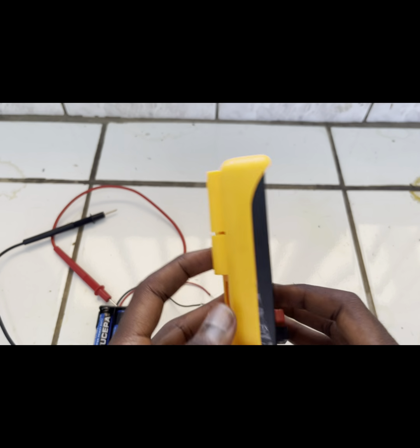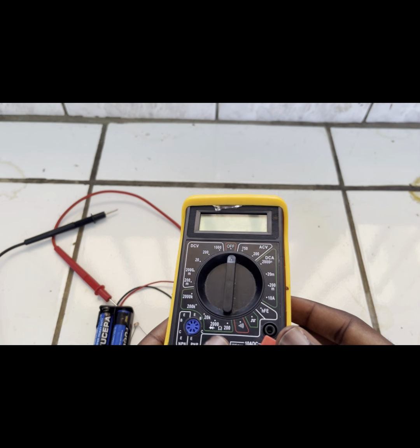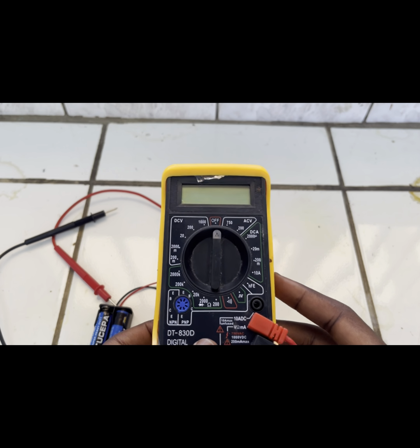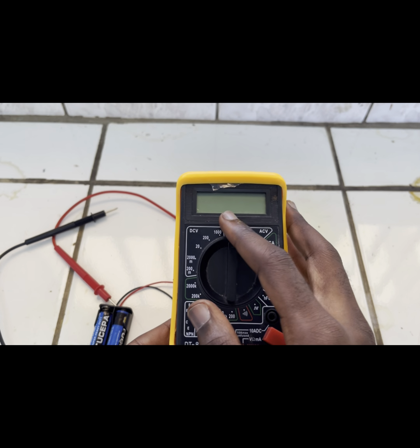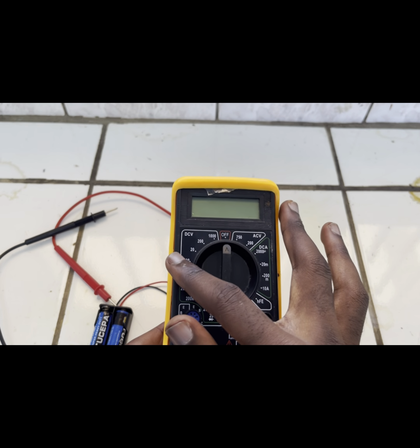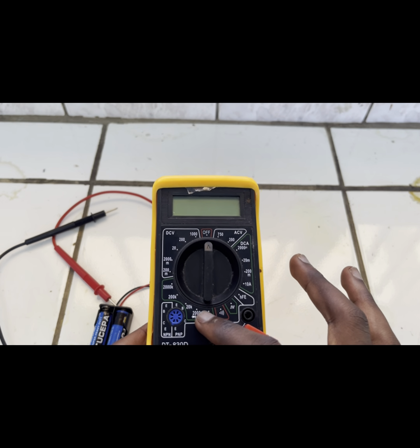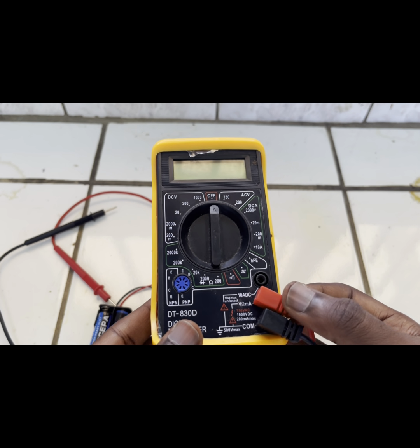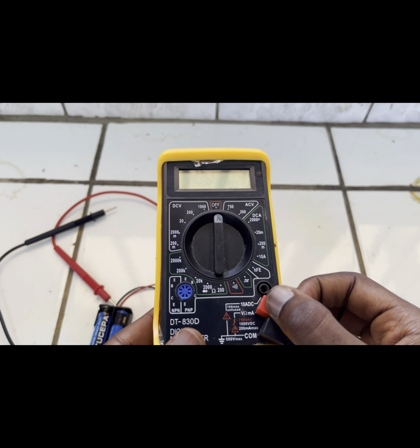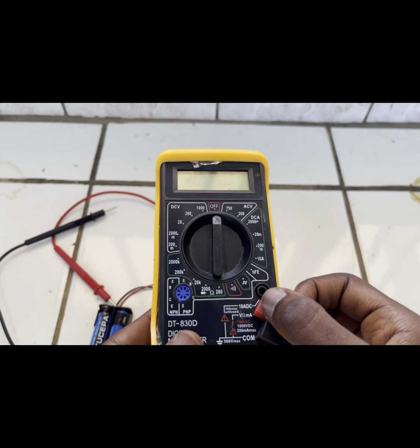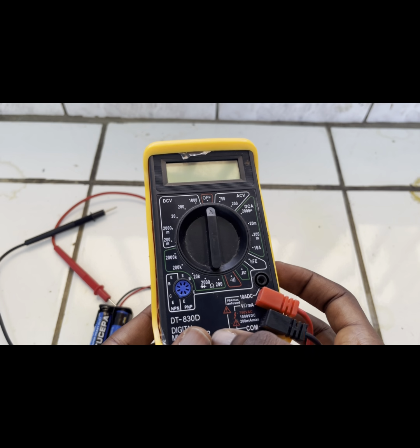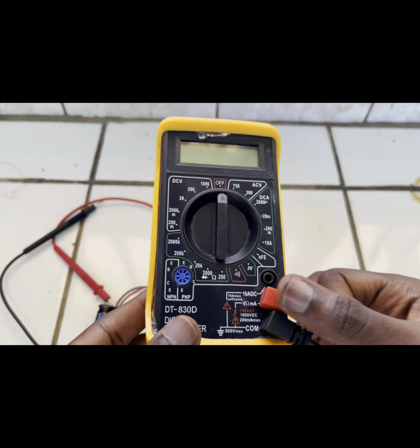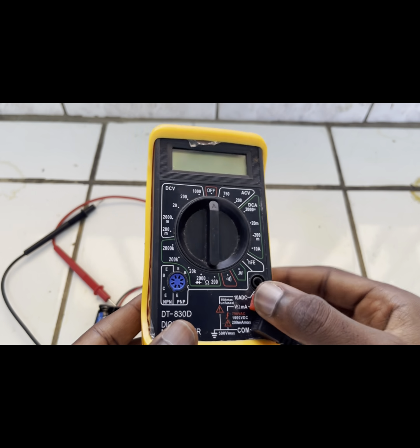Okay, students, as you can see, the main equipment for this station is a multimeter. If you don't know how to use a multimeter, you cannot do the station. The multimeter is divided into four sections. Here we have the entries: AC, DC, and COM, which is like the neutral. So it's always preferred to put the black lead here, and the red one, the positive, here.